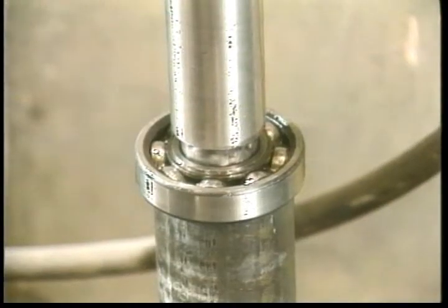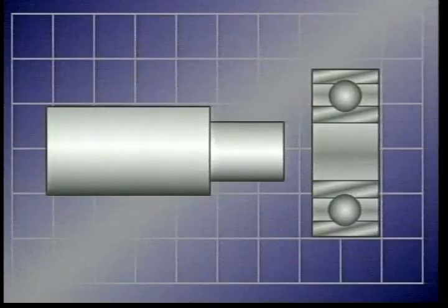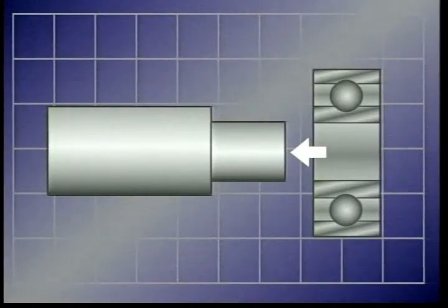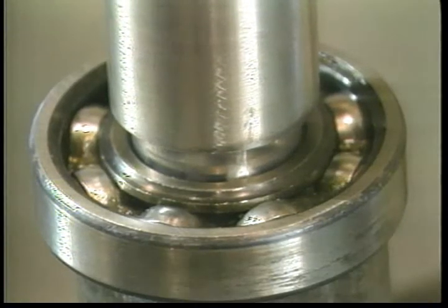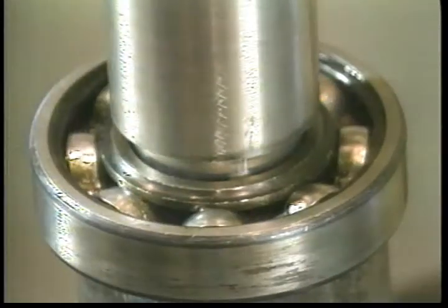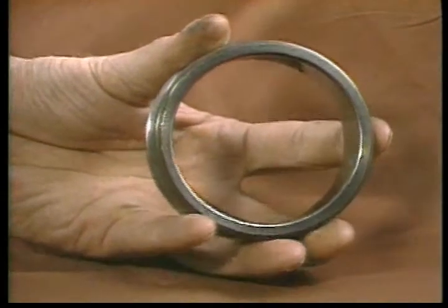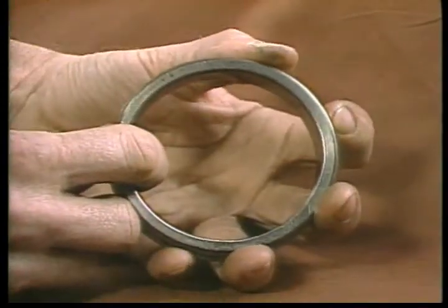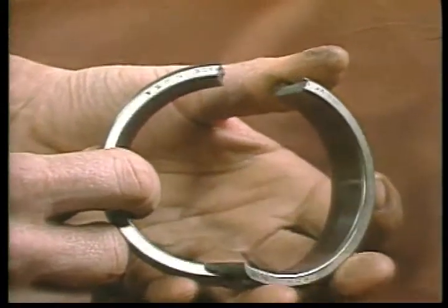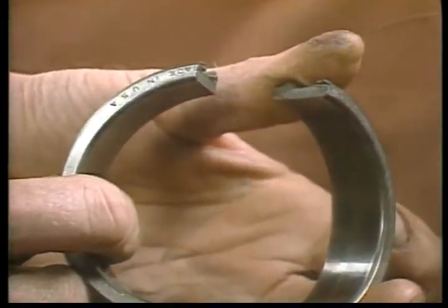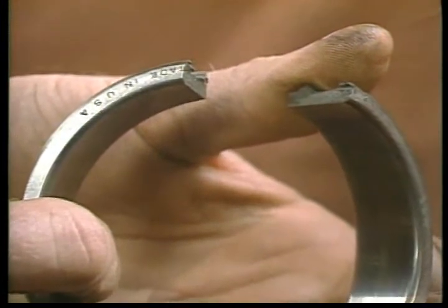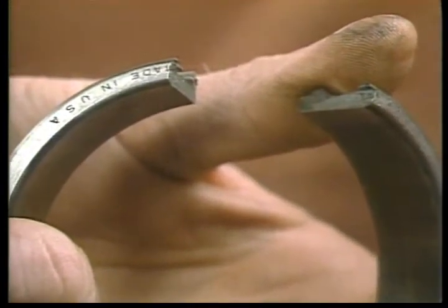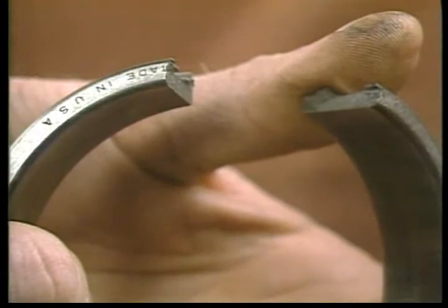Press fitting is another common way of locking a bearing ring in position. The shaft is supplied slightly larger than the bearing's inner ring, or the bore is made slightly smaller than the bearing's outer ring. Press fitting a rolling element bearing puts very high forces and stresses on the bearing. If a bearing is pressed on incorrectly, it will be difficult to take it back off without destroying it. Or if pressed on incorrectly, a bearing may be only slightly damaged, so slight that the damage goes unnoticed, but the bearing still fails prematurely. In some cases, of course, improper press fitting can actually break a bearing.